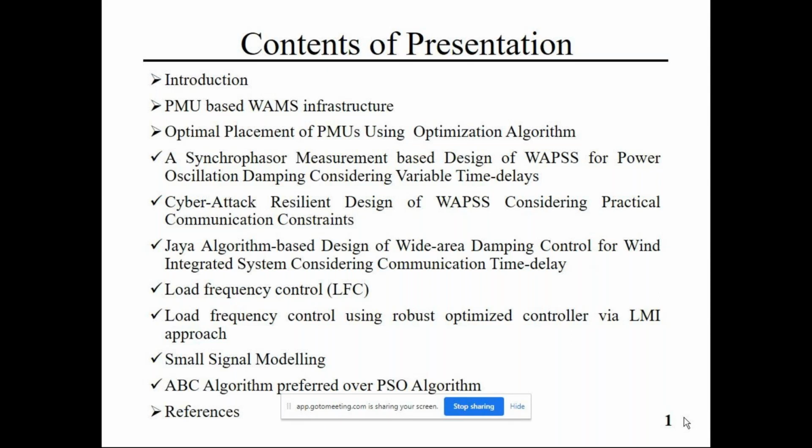Now, as I told you, the communication infrastructure, when the power network is being dominated by the renewables and with the augmentation of a lot of power electronics converters, the communication infrastructure also plays a crucial role, because the PMU, for instance, IEEE C37.118 and the different intelligent electronic devices, that is IEC 61850, the communication protocols, and you have the sampled values. So that means you have the rigorous analysis of the communication infrastructure. Apart from that, the congestion, routing, priority of the message transfer, all has to be taken into consideration.